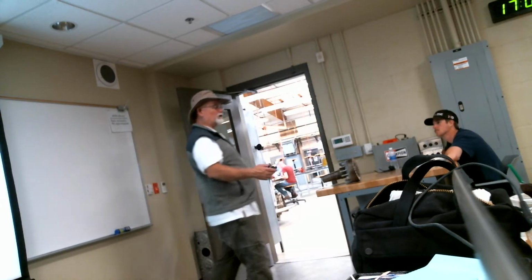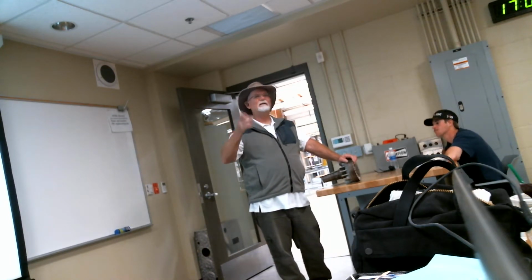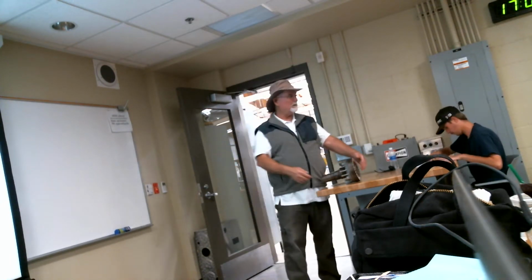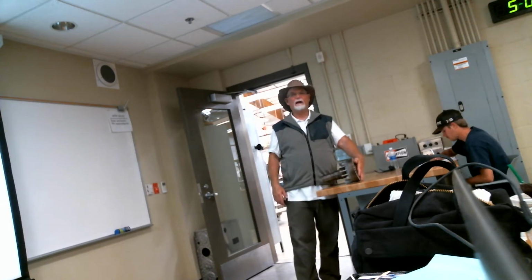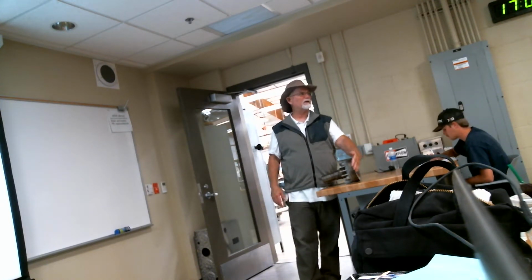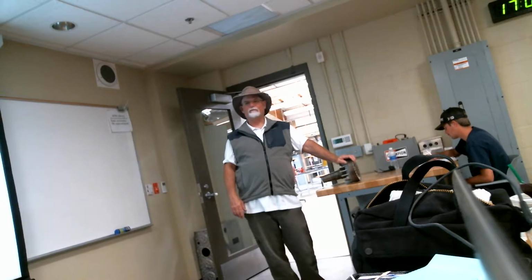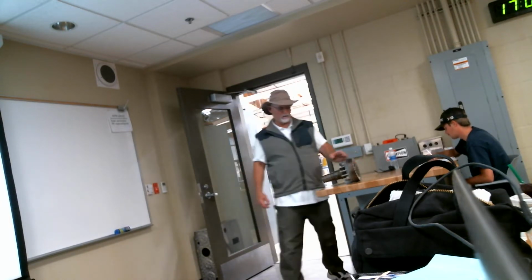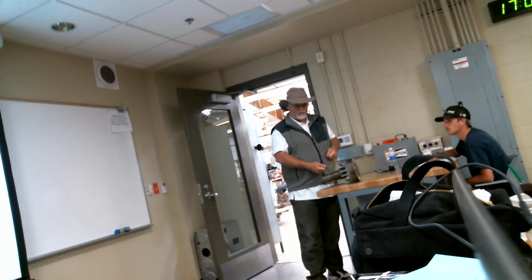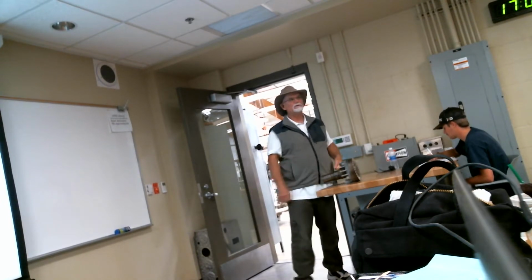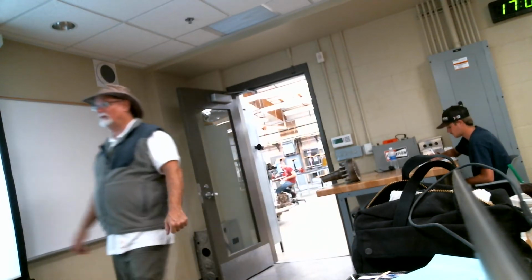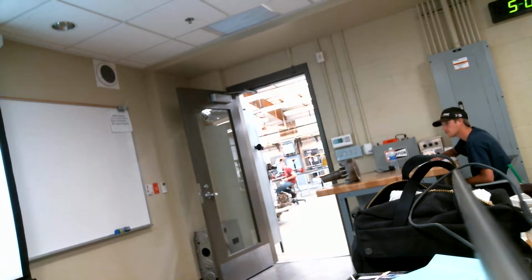This guy, when I first turn it on, lots of slippage, a whole bunch of current. Once it gets up to speed, its current's going to start dropping because this guy's going to catch up. And it's going to start inducing less and less current in these windings, less load on the initial inciting windings. Don't just sit there fat, dumb, and happy until you put your drill into the grinder and start grinding it down just to annoy your general teacher. Okay. All right.